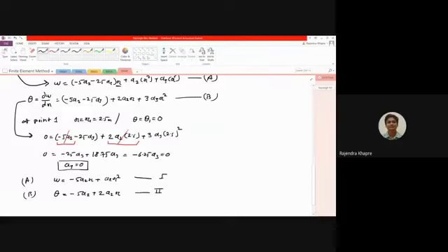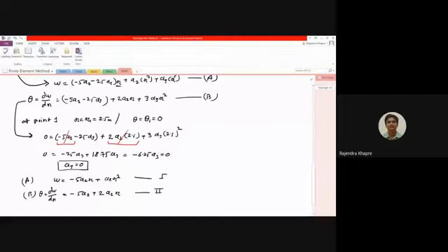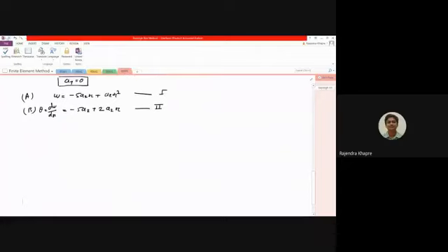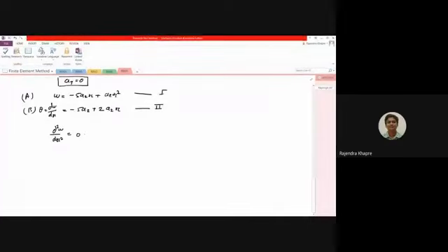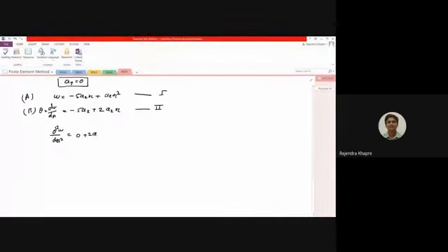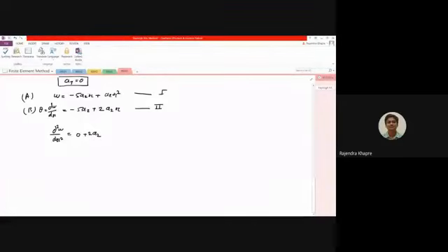Right? So let me slightly erase this and write down over here. So theta is dw by dx, not x square, only x, okay? dw by dx, right? Now in case of calculation of the strain energy, we require d square w by dx square, isn't it? So we have to go for one more derivative of this. So we are going for d square w by dx square. If you solve this, this term will be 0, and here what you are going to get is something like 2 times A2.